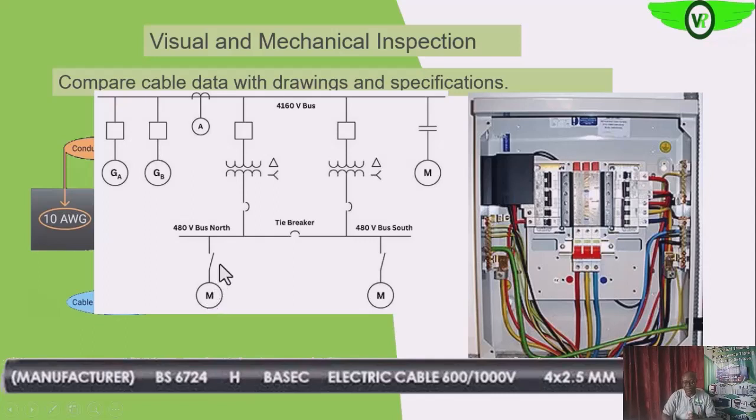Remember, we are looking at low voltage cable, which means that we are going to be using those cables in this section of the circuitry, that is from here down to here, because this is a step down transformer. Are we getting it? Now what we need to do is to check this parameter, the voltage rating of the cable, that it matches that of this section.